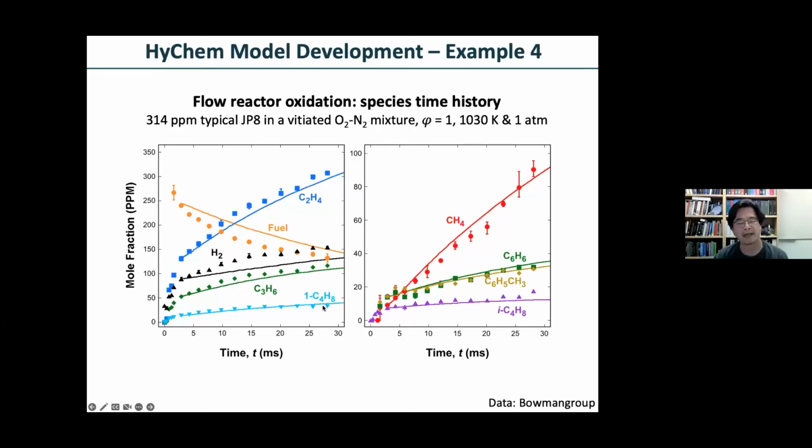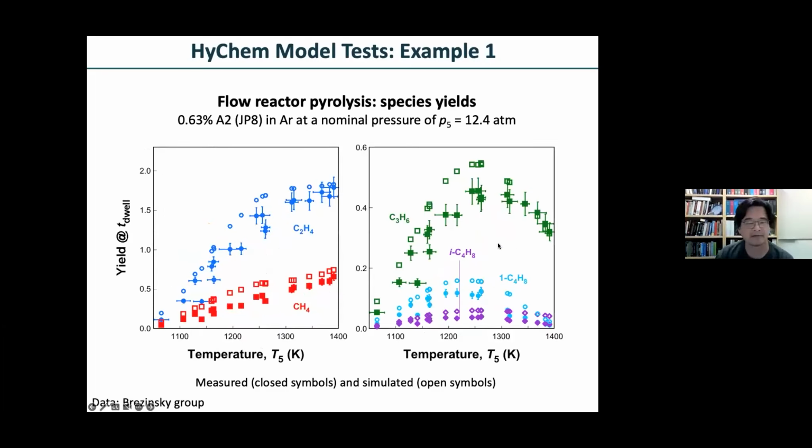The propane and 1-butene measurements allow us to determine the ratio of these species, their yield to ethylene. Those are the lambda properties, if you recall. We have benzene and toluene. So the inverse of this problem allows us to fully determine those HyChem model parameters.